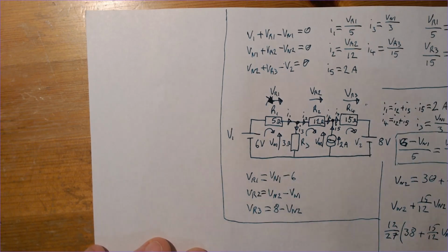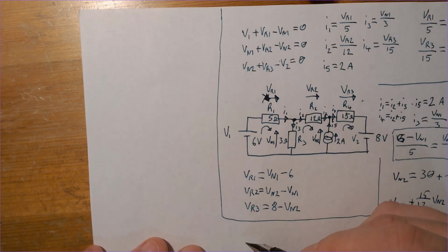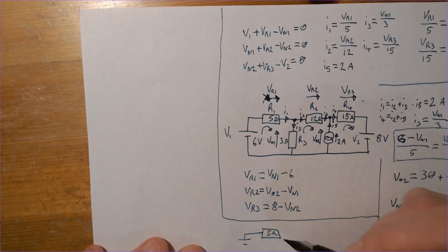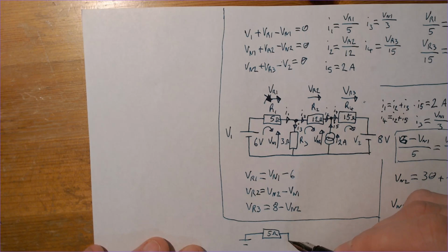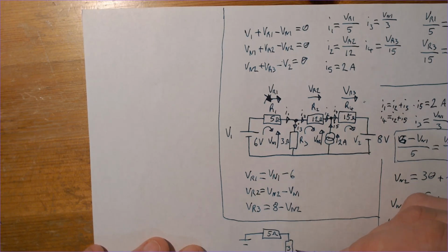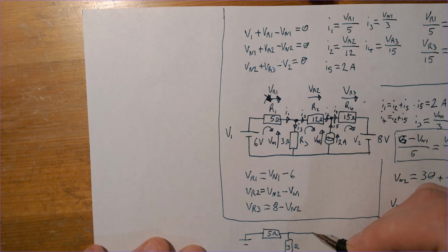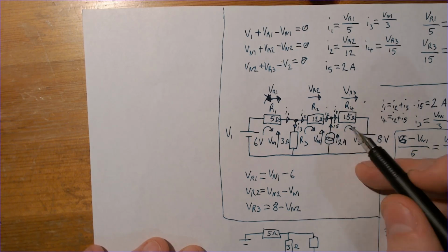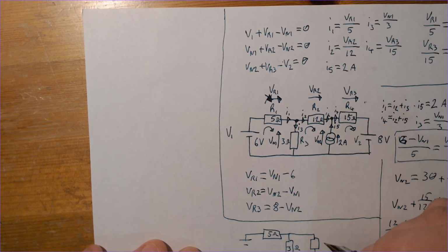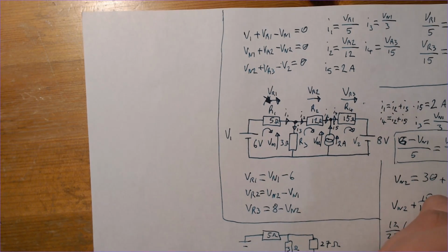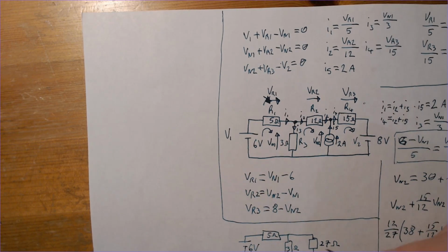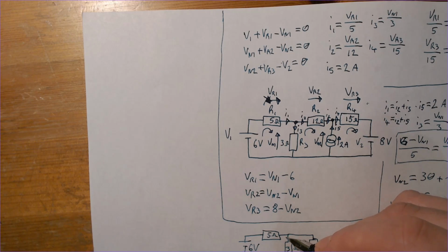So we can draw that out as, let's do it down here, 5 ohm resistor, 5 ohms, and we're looking at this voltage here. This is 3 ohms, and this is in parallel with this resistor, which is made of these two in series, add together, so that would be 27 ohms, and that is 6 volts. And we're looking for the current flowing into here.